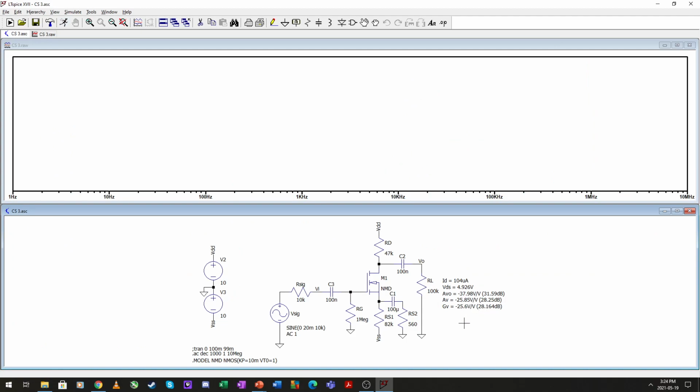These are a little bit higher, but the output impedance of this transistor will be much higher with this source resistor right here. Not totally in the scope of the work that we are doing right now. So the output impedance of this transistor increases when our source resistor is not bypassed like this.